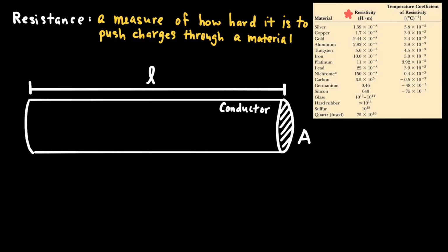The first 5 or 10 materials listed there all have an exponent of times 10 to the negative 8. So materials like copper that have very low resistivities will have a very low resistance and allow for there to be a large current. If there's more resistance, I get less current. If there's less resistance, there's more current. And so surely there must be a relationship between the resistivity and the resistance that depends upon the physical properties of the material that I'm working with.